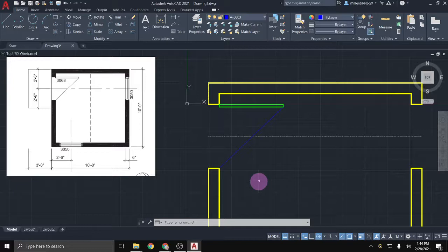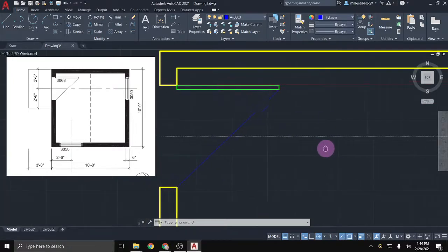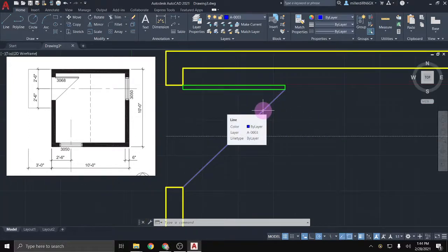With our big CAD project, choosing a different color is going to really screw up what's called a color plot table, in which the printer reads different colors as different line thicknesses. So when it sees the color yellow, it prints it out with this thickness. When it sees the color fuchsia, it prints it out with another one. So don't mess with the colors in that project, but if the blue really is getting to you that bad, I guess feel free to pick a different color. But that's how you would do it with a line. Pretty simple, pretty straightforward. Hopefully didn't blow anyone's mind there.